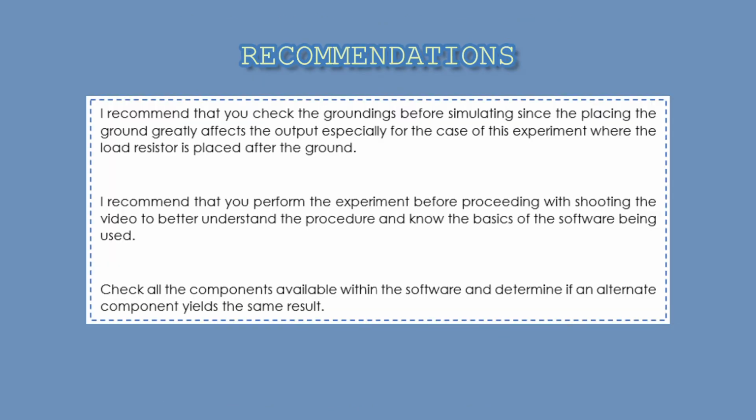Recommendations: I recommend that you check the groundings before simulating, since the placing of the ground greatly affects the output, especially for the case of this experiment where the load resistor is placed after the ground. I recommend that you perform the experiment before proceeding with shooting the video to better understand the procedure and know the basics of the software being used. Check all the components available within the software and determine if an alternate component yields the same result.